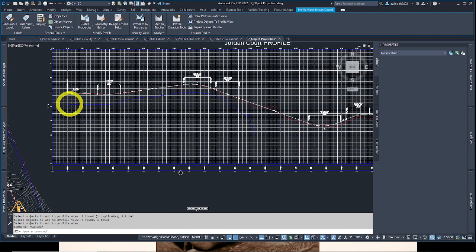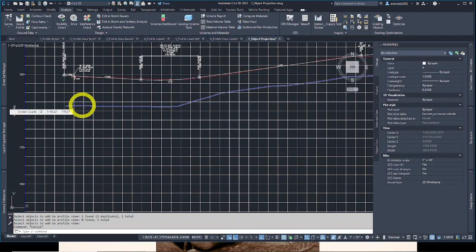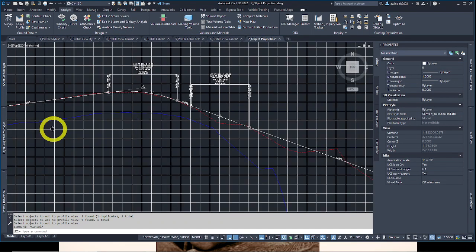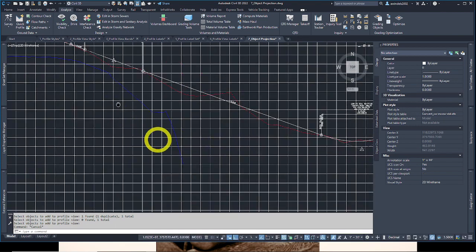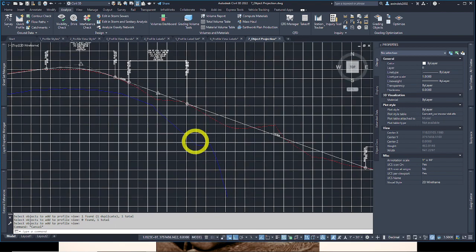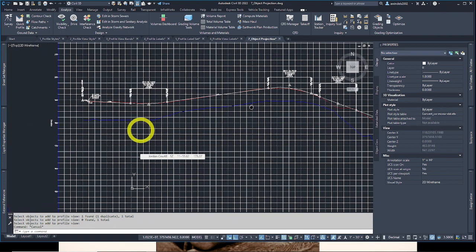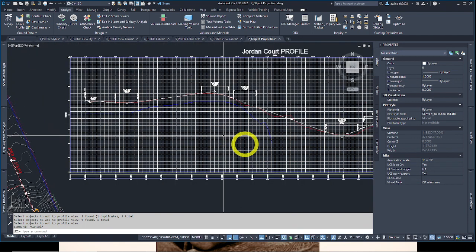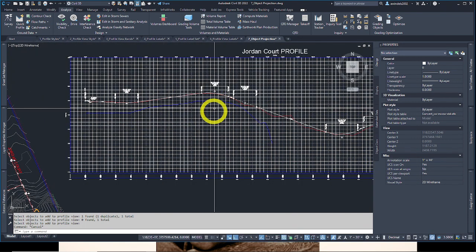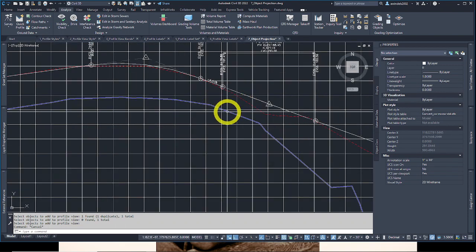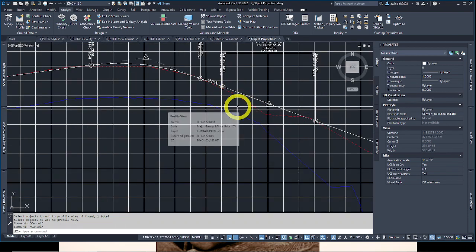You can see the water line did project. It's a 3D poly with many nodes. It followed in here. It's probably like a 1 or 2 inch water line underground. You can see it's projecting in here. That's pretty cool. That helps us do some design inferences, draw our road properly, have the correct distances here for coverage, so the water line doesn't freeze, various things like that.